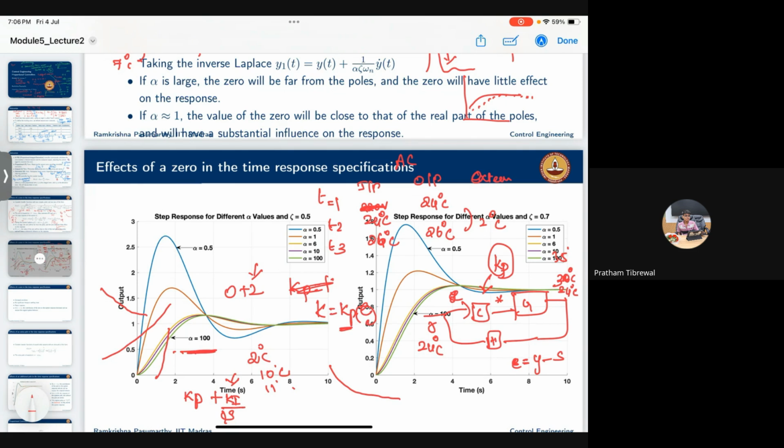Then you can introduce a differentiation controller, which brings down this overshoot, so the system does not respond in a very dramatic way even though the error is not zero. It will take the system slowly, but without any integral action, if you introduce this differentiation alone, then it may make the system sluggish because it is bringing down the response, right? It is not letting the system overreact. So it may create a delay in the system. So you should be very careful while choosing these gains.